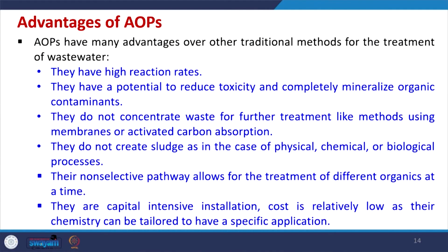The advantages, we have already discussed a few of them, but there are other advantages also over traditional methods for water treatment. These AOPs generally have high reaction rates. That means the reactor configuration will be smaller. The higher the reaction rate, the faster the treatment. So, within a reactor volume we can treat more water, or if the amount of water generated per unit hour is fixed, we can reduce the reactor volume. They have a potential to reduce toxicity and completely mineralize organic contaminants, which is the key advantage.